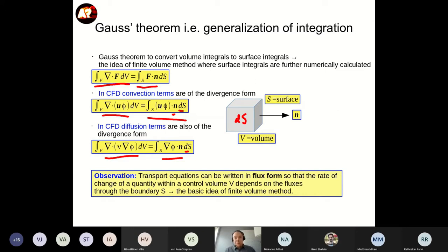And in the finite volume method, you can have arbitrary polyhedra, arbitrarily shaped elements, and by computers you apply the Gauss theorem and calculate the fluxes, and it gets much more complicated than this when you have complex cells and stretched grids, but the main idea is over here. Integrate over volume, apply Gauss theorem, you change volume integrals to surface integrals, and that's it.